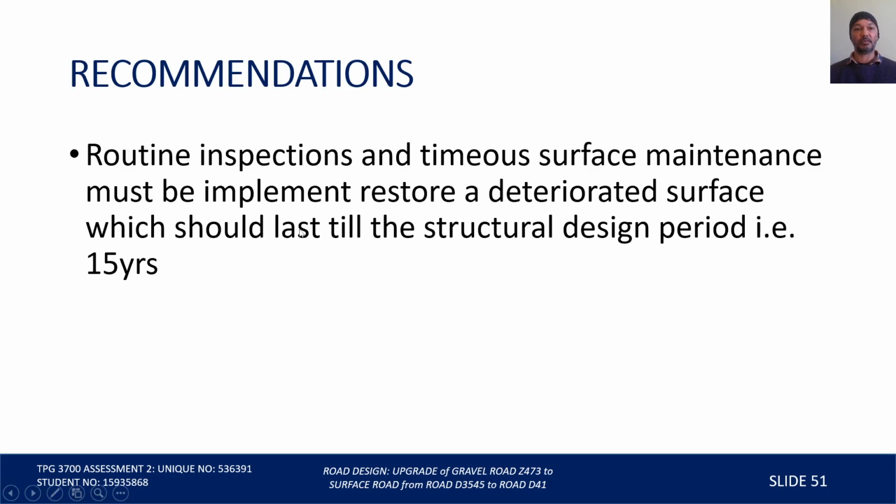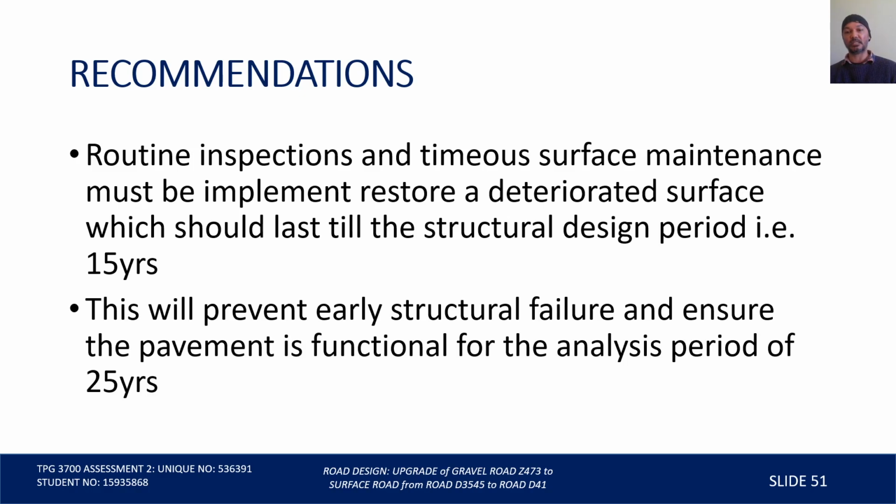So, recommendation: I recommend that routine inspection and timely surface maintenance must be implemented to restore a deteriorated surface, which should last until the structural design period of 15 years. This will prevent early structural failure and ensure the pavement is functional for the analysis period of 25 years.